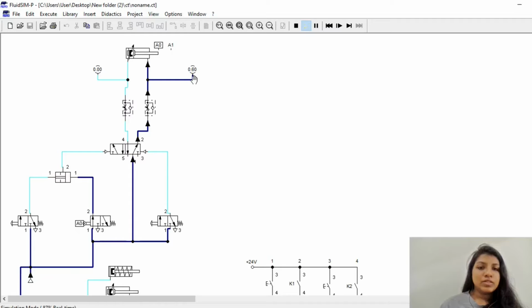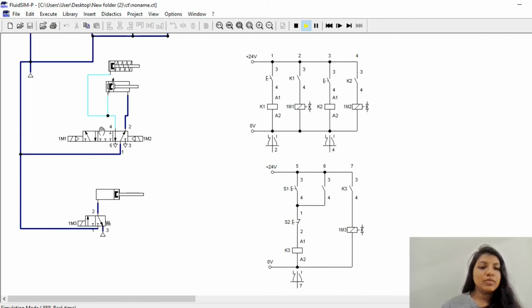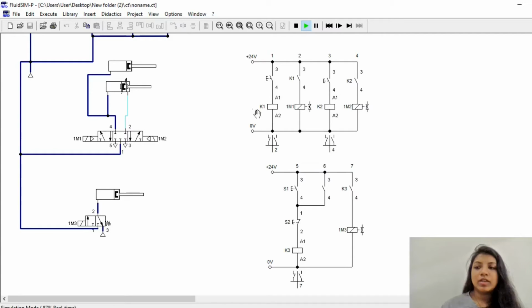The manometer shows 0.6. This is the workpiece, how it sits in position. This helps the workpiece sit in position. It moves forward and retracts back by the use of the solenoid system. This is the 5/3 way system, which helps the workpiece set in position to make a hole.